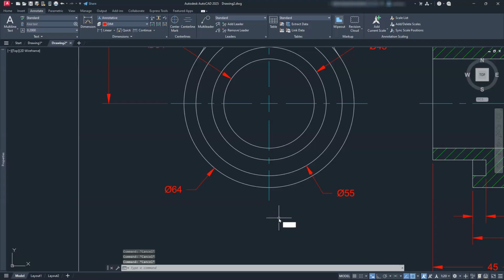I'm going to start off by using the Polyline command. So PL enter. My starting point, I'm going to click here, and then it asks me for my width or how I'm going to create this. So I'll start off with the width. Let's see, I'll use my starting width as 3, enter. My ending width will be 0, and then I just need to tell it which direction. Let's go ahead and turn this ortho back on. So I'm going to drag out this direction, and it looks like about 8. Great. Go ahead and hit escape.